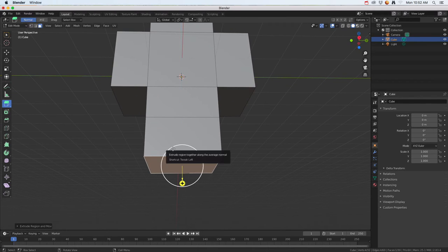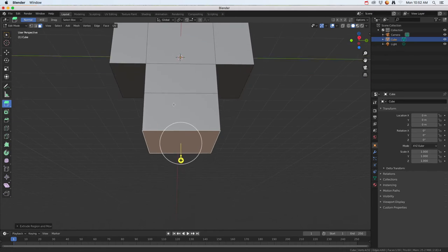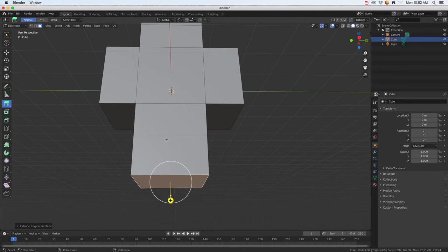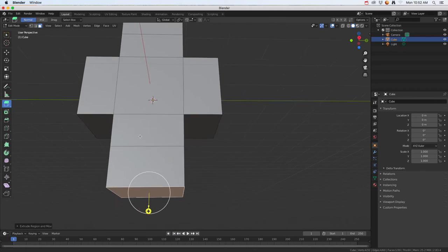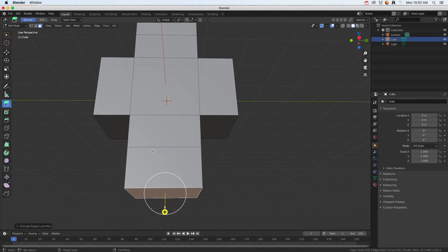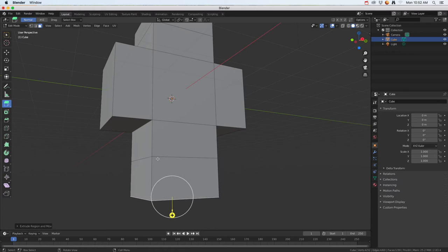So I just did something where I slid the whole area, the pan, and if you hold down shift and press the middle mouse button, that also lets you go back and forth. If you let go of the shift, then you can move around.